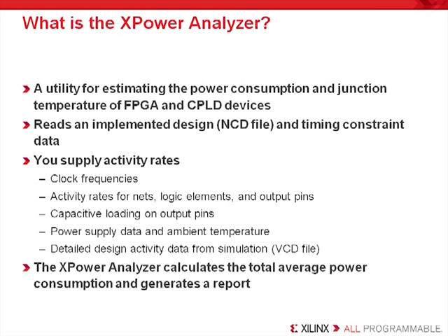While this same information can be loaded manually, it also can be read in from a VCD file, which is a detailed design activity data resource from your simulation tool. A value change dump, or VCD file, is created by a simulation tool, such as Mentor Graphics ModelSim, for example. The VCD file contains information about signal or variable value changes. The VCD can be read by the Xilinx XPower Analyzer to provide accurate power estimation. Note that in order for the XPower Analyzer to match instance and net names from the VCD file to items in the NCD, that is your implement result, the VCD file must be from a post place and route simulation.